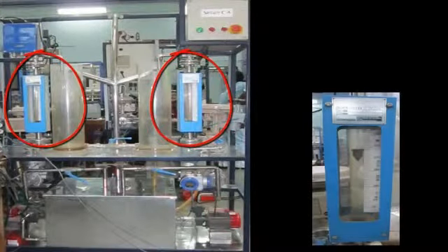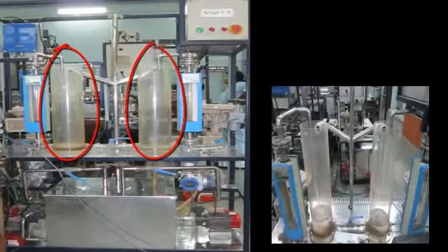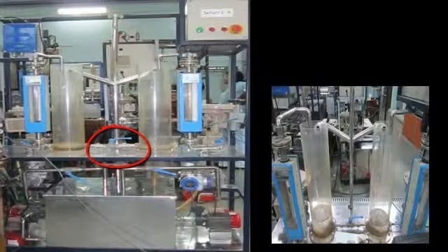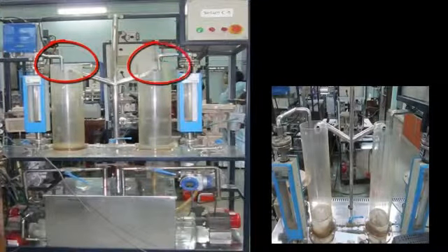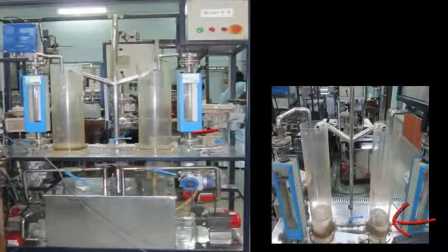The tanks in the interacting setup are two long cylinders of 15 cm diameter and have an orifice constant of 3 × 10 to the power -4 each. These tanks interact through a small pipe which connects them at the base. The water flows into the tanks from the top and flows out through an opening at the bottom of the right tank. The input to the tank on the left is the manipulated variable, and the input to the tank on the right is the disturbance variable. The aim of the controller is to control the height of the water in the right tank.